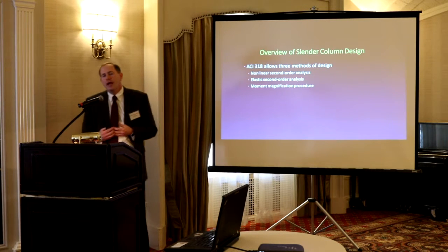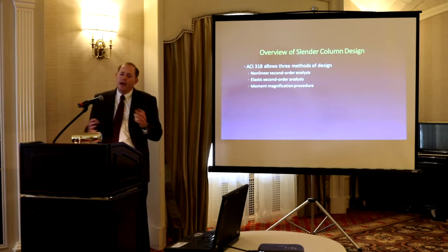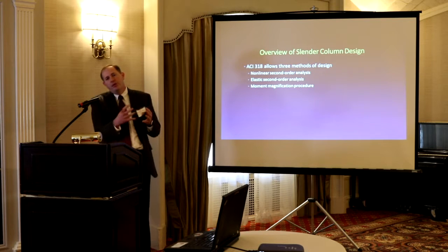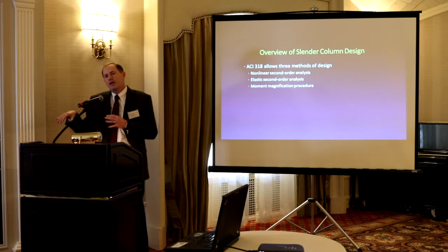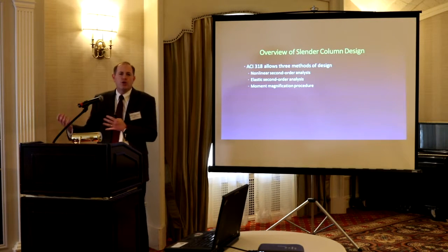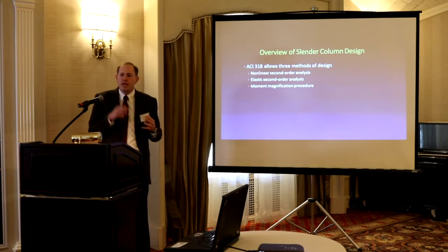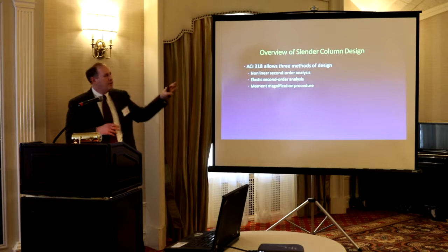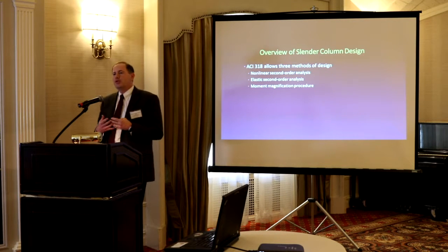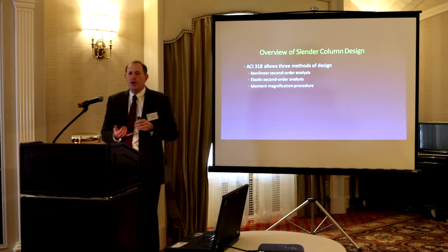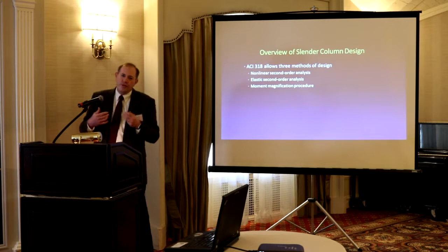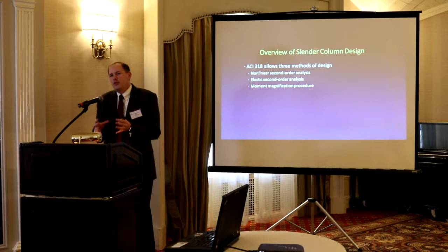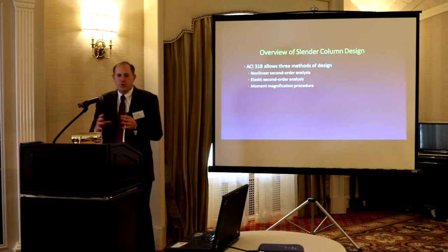And actually, if you look at the code, and I've been on the code for a while, 318-14 is a complete new revision and has that. I'm going to reference 11 right now because I know a lot of places are still using the older code. So I'm not going to talk about the 14 in terms of numbers, and I will talk about what 11 has. But I love to read the provision about this to my students because it tells you in there that as an engineer you have to account for everything: settlement of the foundation, creep, and shrinkage. It's kind of my favorite passage. If you can do that, you can do anything, right? It's just one code provision.